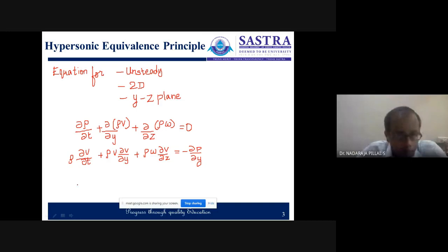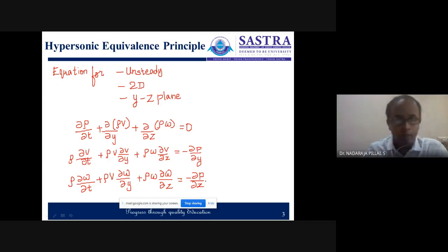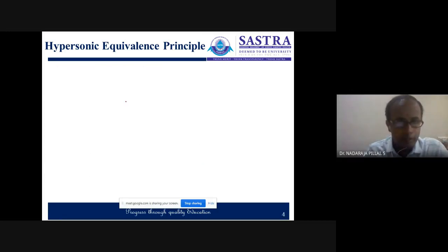Right? Now let us write the z momentum equation: rho into dou w by dou t plus rho v into dou w by dou y plus rho w into dou w by dou z, that is equal to minus dou p by dou z.